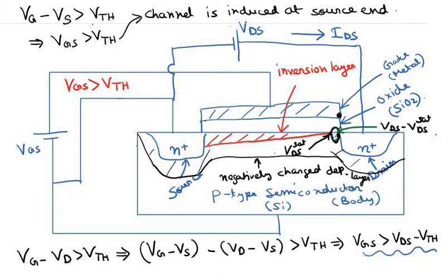Current flow across this exposed depletion region is like the current flow in a reverse biased PN junction. This region where the depletion region is exposed, or where there is no channel, doesn't have any electrons or induced electrons of its own, but it has a very high electric field, so it transfers the electrons which the channel provides from the left.